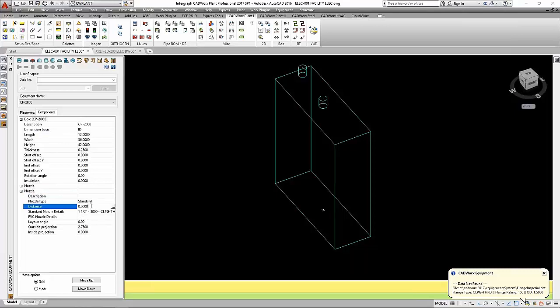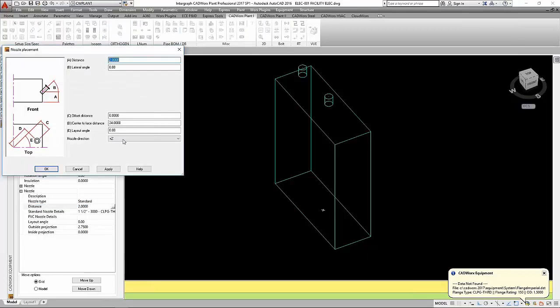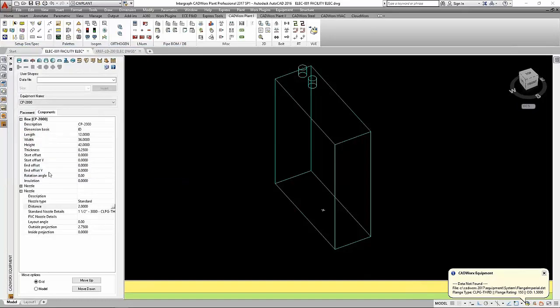So now my task is just to take this 1.5 inch nozzle and position it 2 inches back, and then I'm going to offset this to 13 inches. Oh, that's too close. Let me change that to 10 inches. Awesome. So there's my 2 hubs that I can route Conduit from.